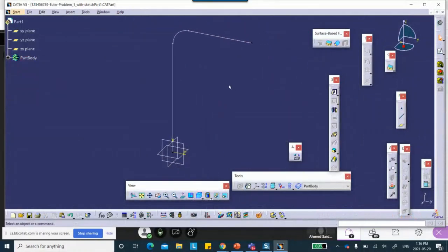This is it. This is your part. Don't try to make 3-dimensional object out of that. One of the nasty things that we do is that we give a drawing which looks like in 3D, and people who are not basically with us, they just show up the last few days of the course before the test. They see a three-dimensional object, and then they're going to make it like that, and then they're going to measure the solid element. No, no. If this problem was given to you and says use the most appropriate element, it's the beam problem, and this is it. This is your geometry. Don't make a three-dimensional object out of that.